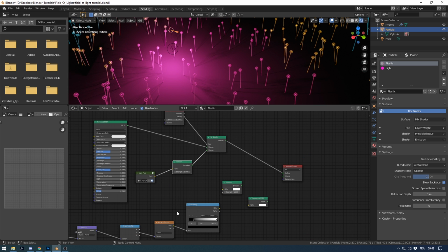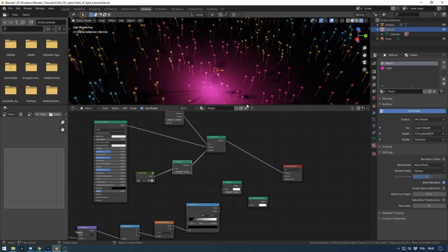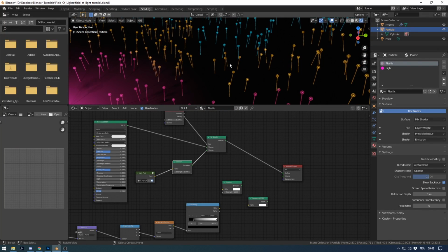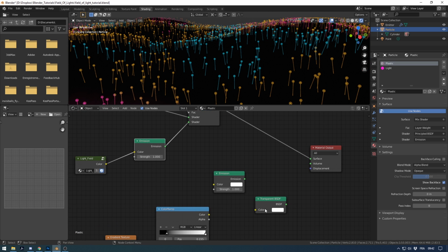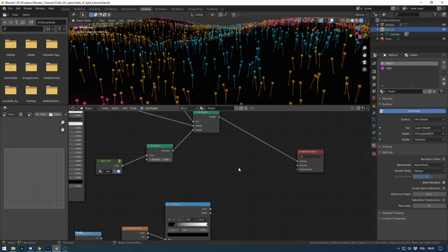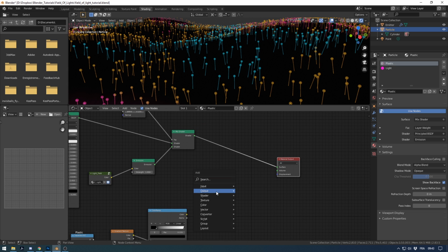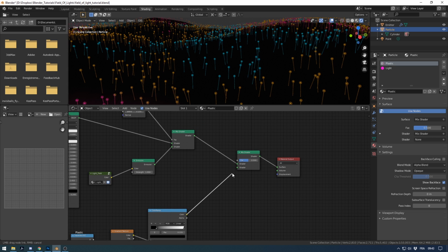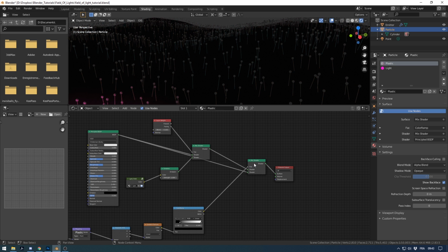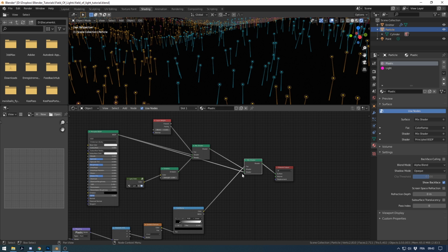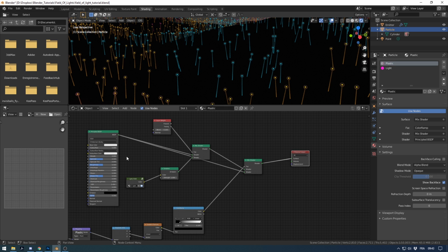now it will be a bit strange to have all these roots with a lot of lights here. So what I suggest now is I will just delete this one, to create another mix shader and connect the principled again here, okay, and I will use the gradient to simulate, to blend the lighten part of this object and then unlighted part of this object.